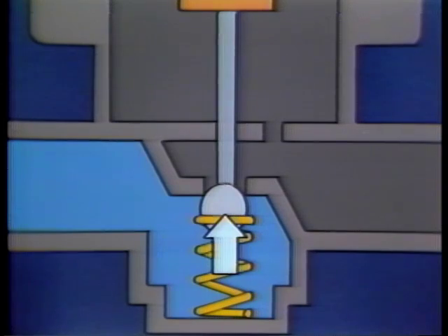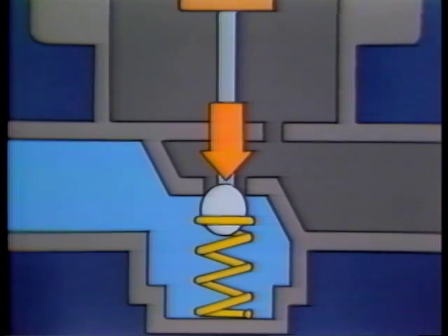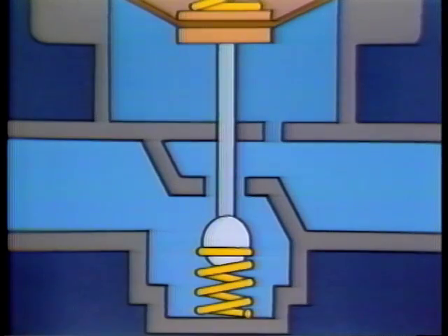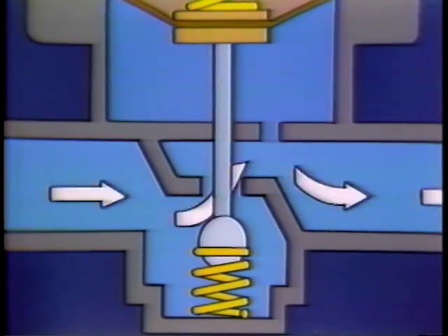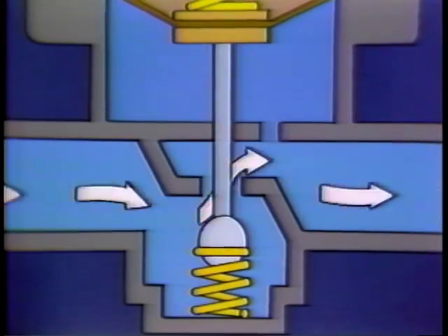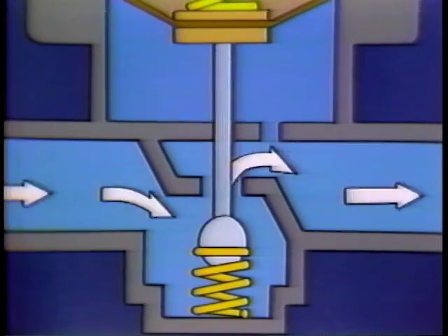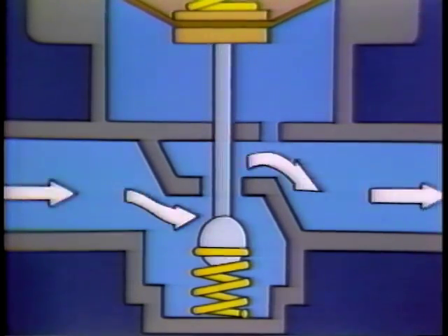In order to overcome this pressure, greater force must be exerted by the set point spring to open the valve, and the spring force pushes the valve wide open. Immediately, there is full flow rate. While the PRV will eventually react to reduce the pressure, its initial response has let loose a high-velocity slug of non-compressible liquid. This is a classic example of water hammer.